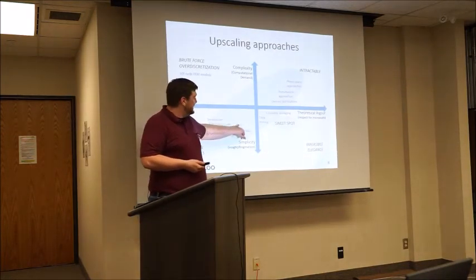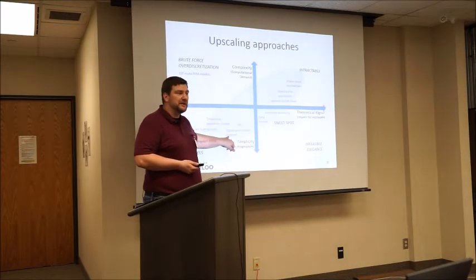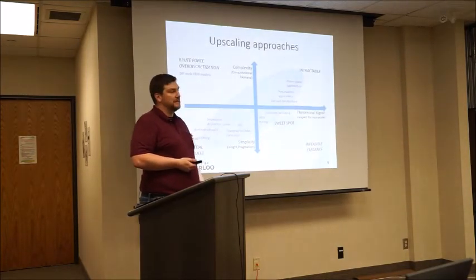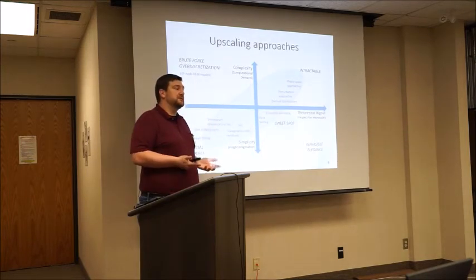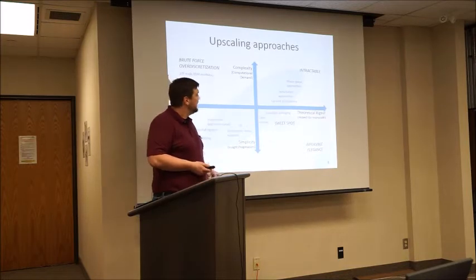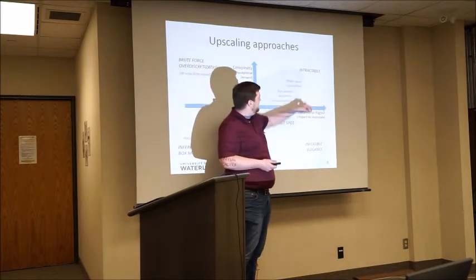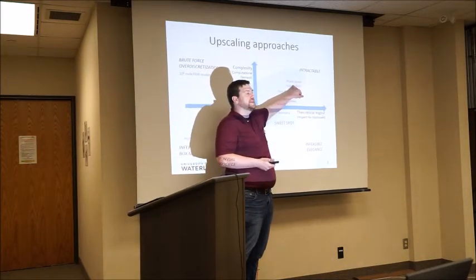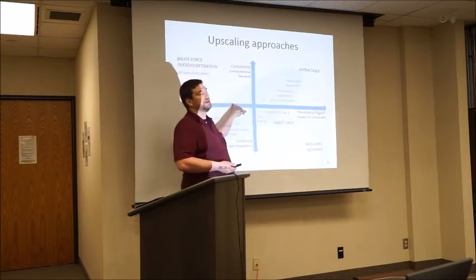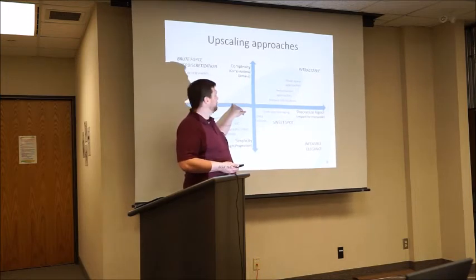There's a variety of techniques which use and respect spatial variability, so they use snow cover depletion curves and a variety of other technical methods that say, we recognize there's subgrid scale variability, but their conceptual model might not be consistent with the microscale. And then there are some very complicated mathematical approaches which, from first principles, start with Richards equation, deploy a whole bunch of averaging tools, and end up with almost impossible equations to solve. So they get here, and then they immediately have to backtrack to here to make it a solvable mathematical problem.